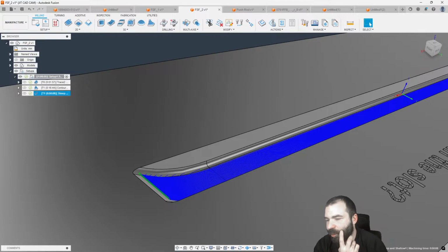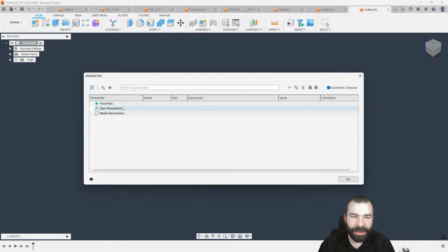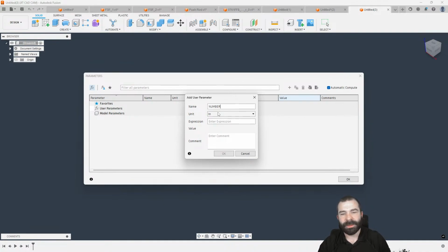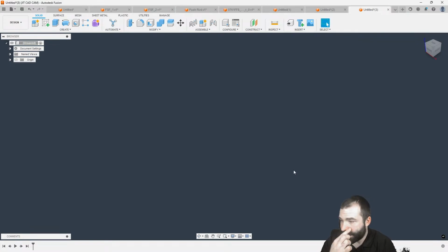All right. Is there a way to create a polygon in Sketch where we decide a number of sides by a parameter? In that case, it works when it's defined, but later when I edit the variable, the sketch isn't updated. Let's go ahead and see. We can find out pretty quick. We want to create a parameter, and we want to create our own user parameter, and we'll just call this number of sides, and this is going to be no length or no units. We're going to start with 6. The reason why that's no units, just so you guys know, is because that is an integer, so it's got to be a solid number.